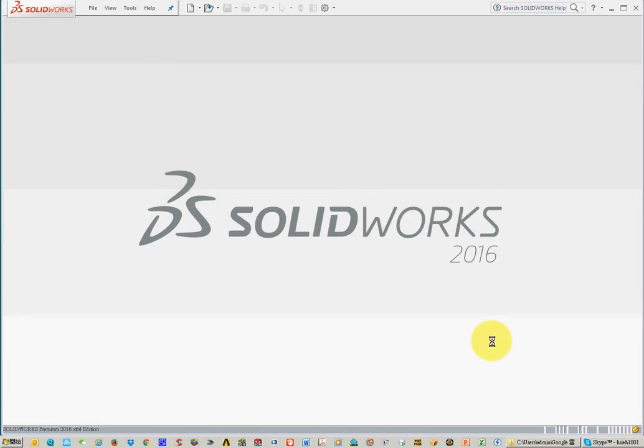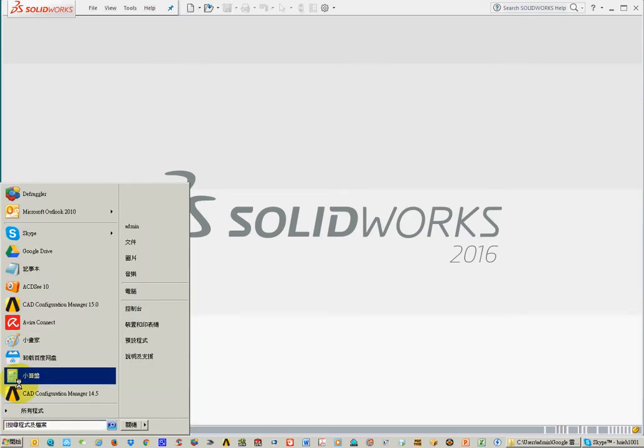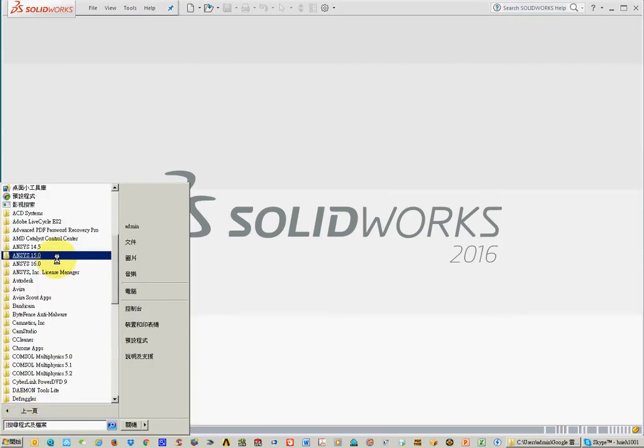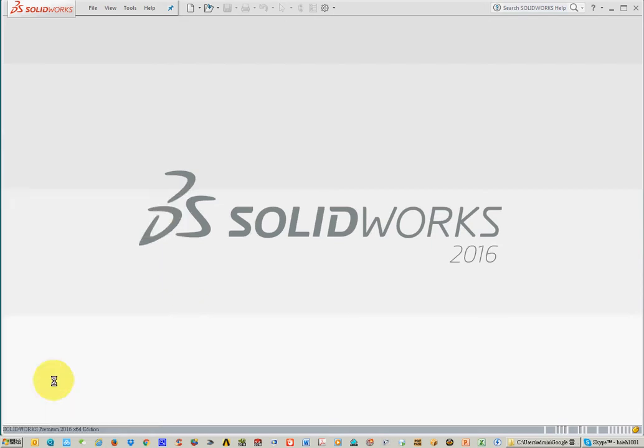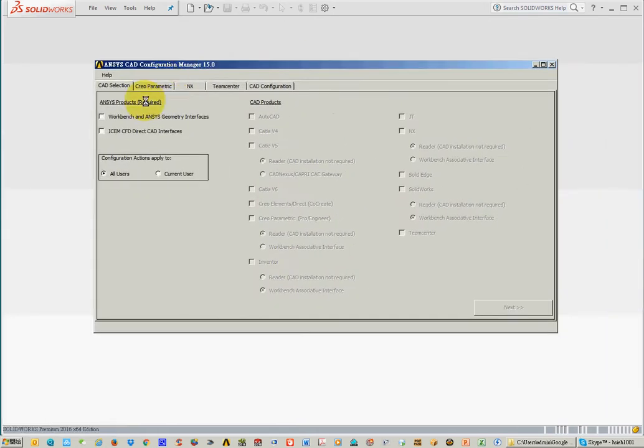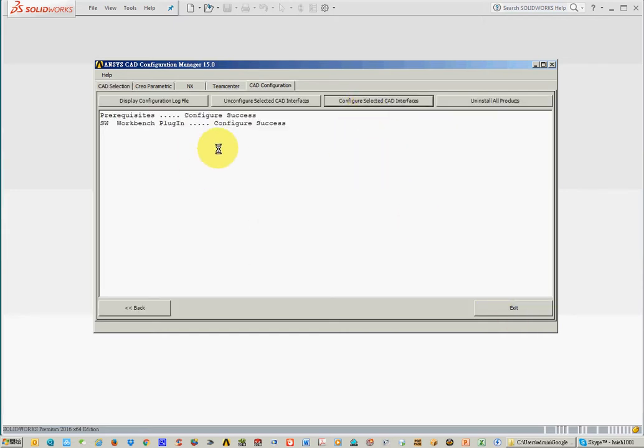ANSYS Simulation, Lecture 1: the structure of CAE analysis. For the first time you run ANSYS, make sure that ANSYS is linked or connected with your CAD system. Choose ANSYS Utilities, CAD Configuration Manager, and you can connect or link Workbench with the CAD system. And make sure that the configuration is a success.